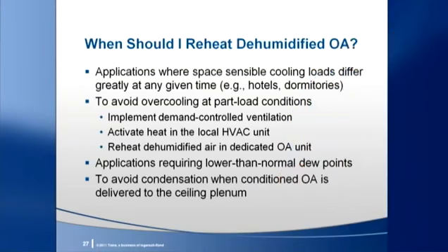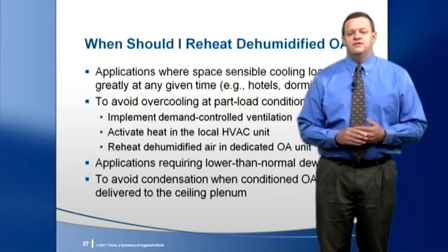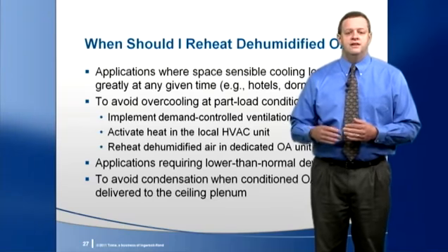Finally, if the conditioned outdoor air will be delivered to an open ceiling plenum near the intake of each local unit, the dehumidified air might need to be reheated to avoid condensation. In this case, it's a good idea to reheat the dehumidified air to a dry bulb temperature that is well above the expected dew point in that ceiling plenum.